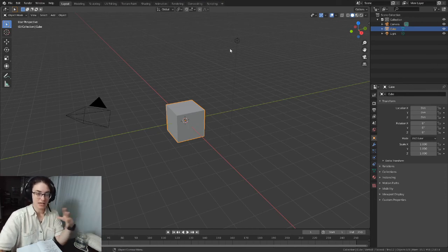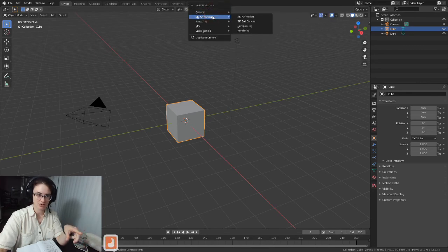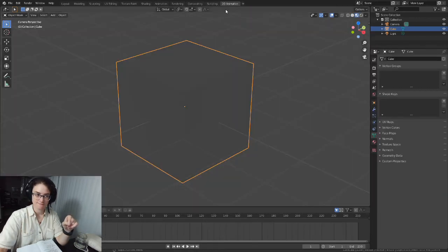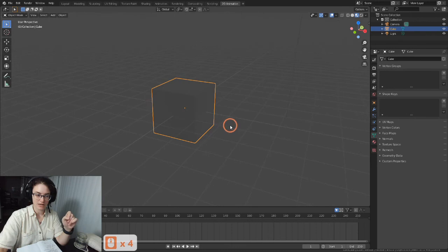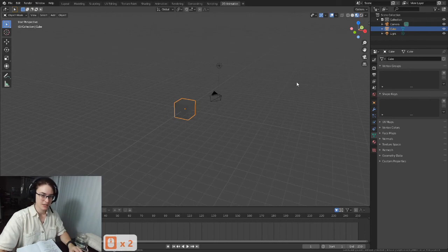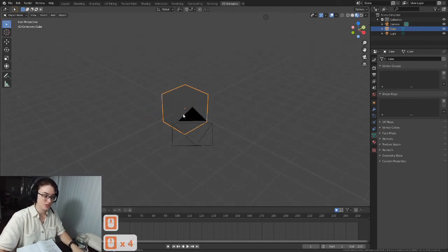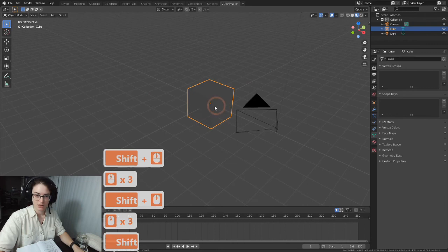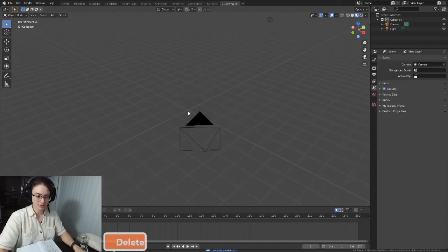And first thing I want to do is actually bring up a 2D animation workspace. So even though I have the general one open, let's make a workspace for ourselves. So the very top, at the end of all the workspaces, there's a plus sign. You could pull in a 2D animation one. So now this is like the screen that would come up if we open the different Blender file. This is going to have all the tools we need for using our Grease Pencil. Right away I'm just going to delete my cube.